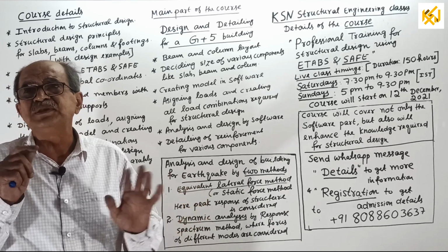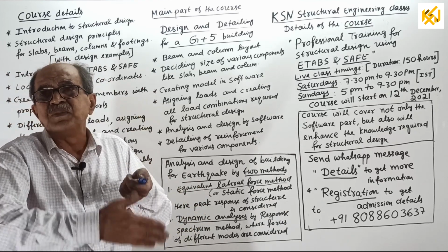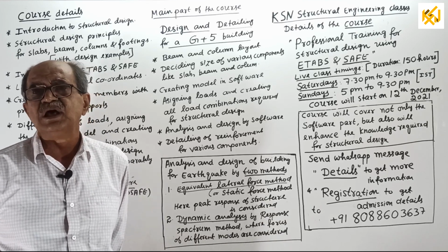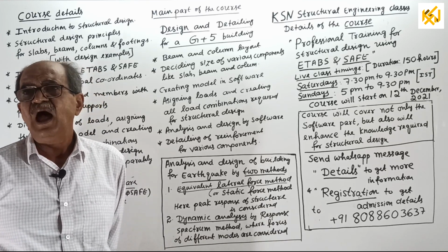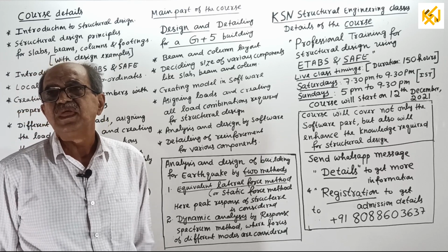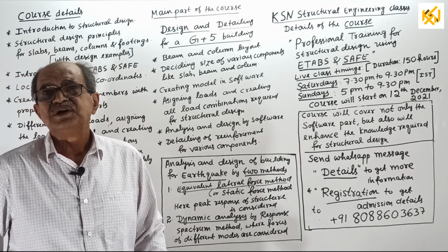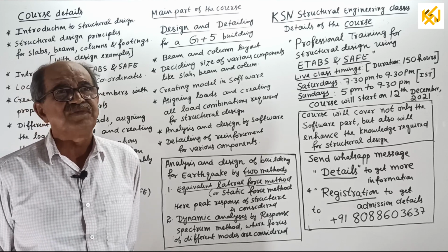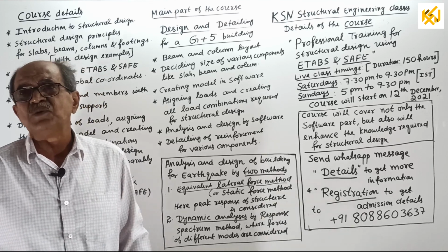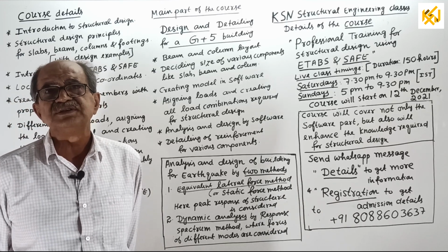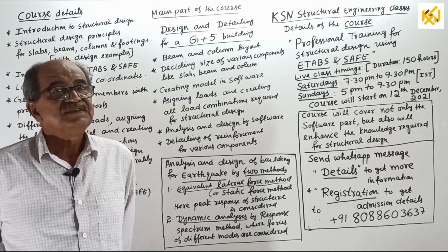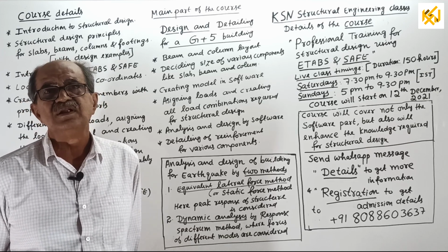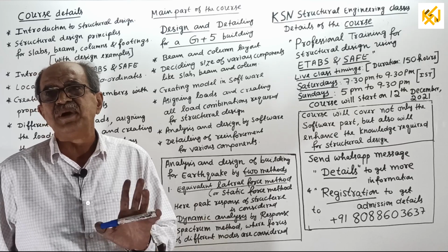But during this process, cross-section of members will be subjected to section forces, namely axial force, shear force, bending moment, and torsional moment. Now, section forces cannot be transferred, they should be resisted, resisted by member cross-section only. Resistance of member cross-section for section forces comes under strength. Second parameter is serviceability, no excessive deformation. For that, codal requirements are there.